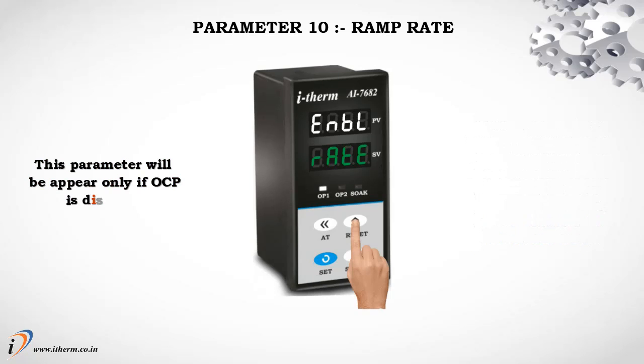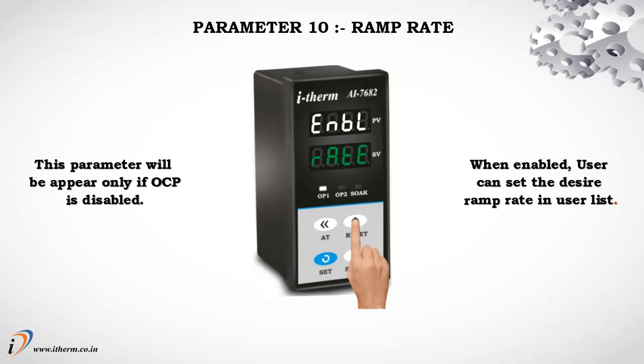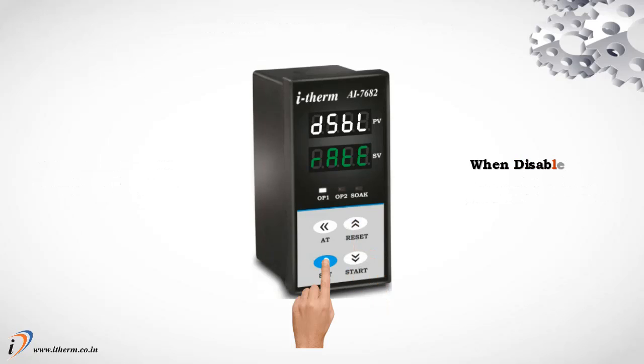Parameter 10, Ramp rate. This parameter will appear only if overshoot control point is disabled. When enabled, user can set the desired ramp rate in the user list. When disabled, this parameter will not appear in the user list.